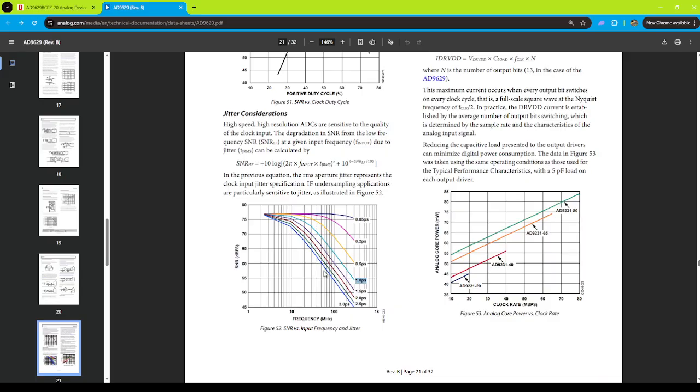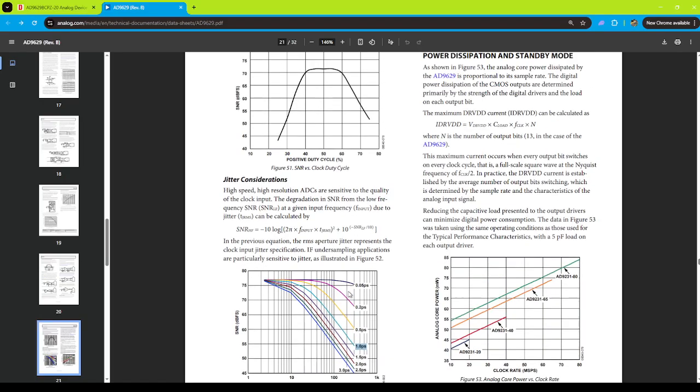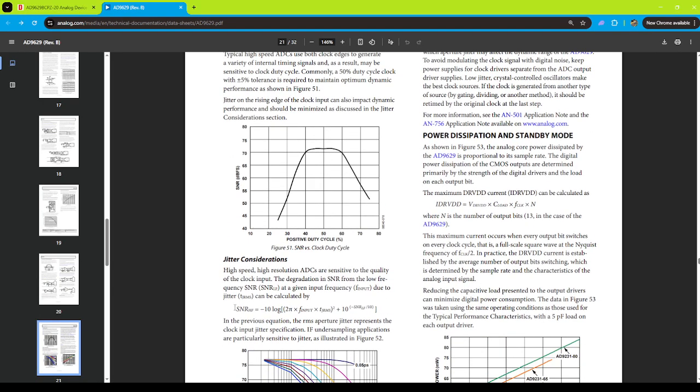And if you have worse jitter, we need jitter in the femtoseconds, like 500 femtoseconds. We need this type of jitter. Yeah, you need femtosecond level jitter. If you're under 10 megahertz, I mean, it's okay. But if you're over 10 megahertz, for sure, you're going to have to go under 1 picosecond of jitter. It comes from this famous equation here.